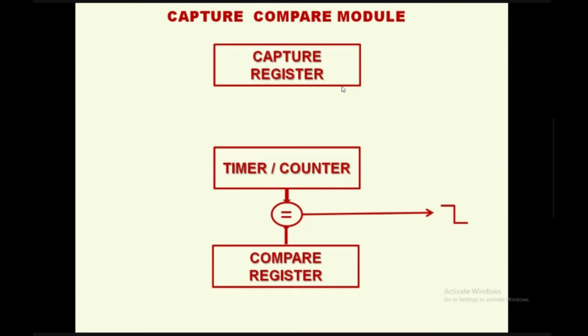Okay, anyway, we have to measure the PWM. PWM has to be measured means what? The duty cycle needs to be measured. The measuring has to happen in microseconds and milliseconds. Again, to measure some activity which is happening in microseconds or milliseconds, you have to make use of a timer. That too, capture registers will fulfill that requirement. Okay, how does this work? Let us quickly refresh this.